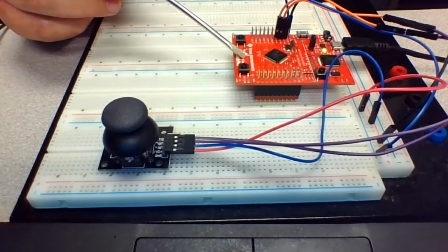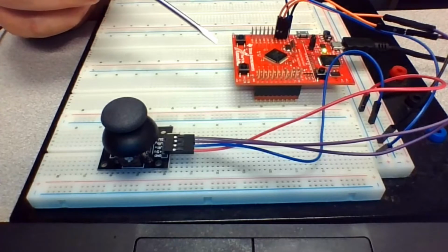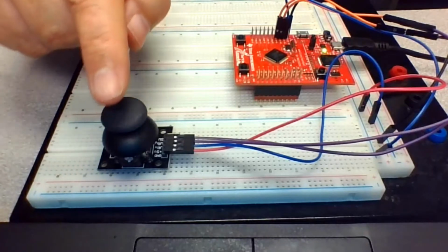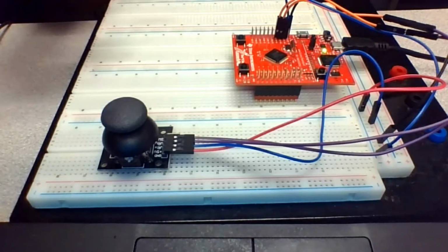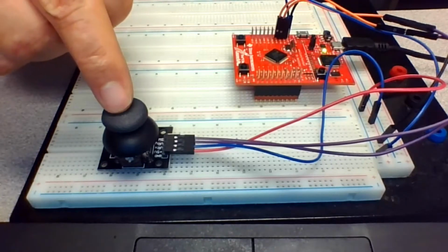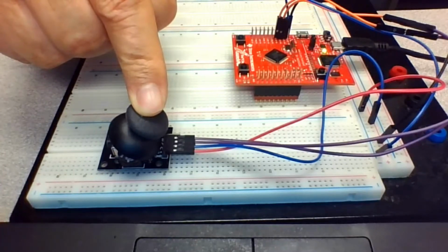Because the launchpad has a 12-bit analog to digital converter, the value that you get on the X pin should be between 0 and 2 to the power of 12, which is 4096. So if I change X or Y, it doesn't matter, because I connect these two pins to the analog to digital converter and read that value from it. Whenever I put X on the left, to the end point here, it gives me the minimum value, which could be 0.